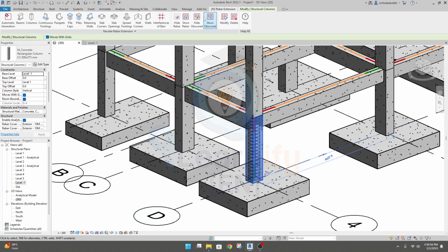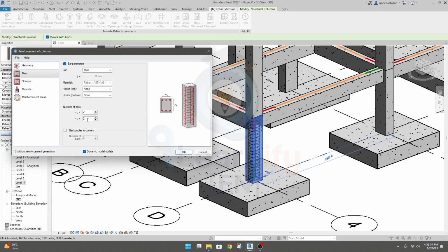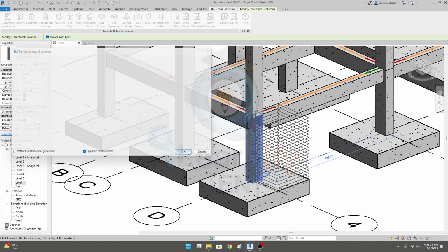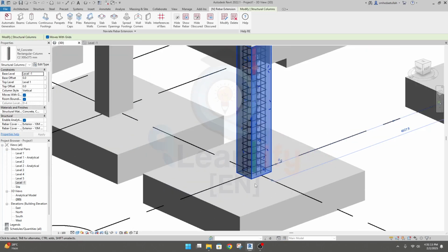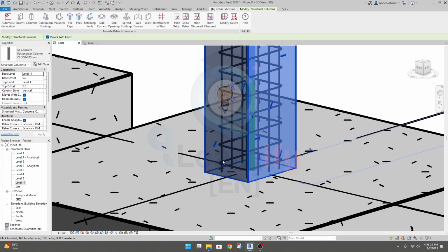Okay, it's selected, then go for modify, and in L direction bar, go to bar, in H we'll provide, let's say, 4 reinforcement and take it. Click OK, and it's done. So in the width direction we have 2 reinforcement, and in this direction we have 4 reinforcement.